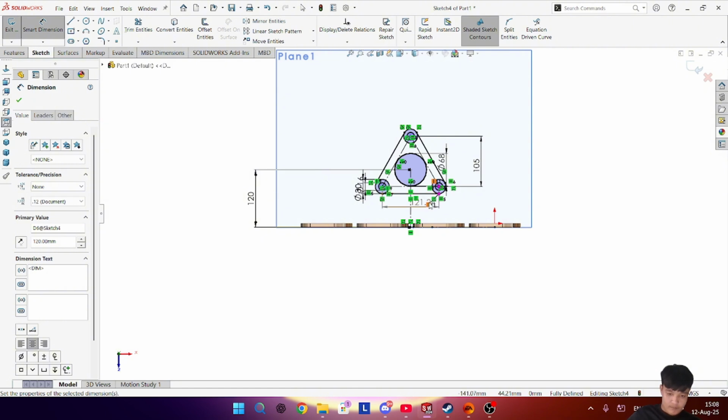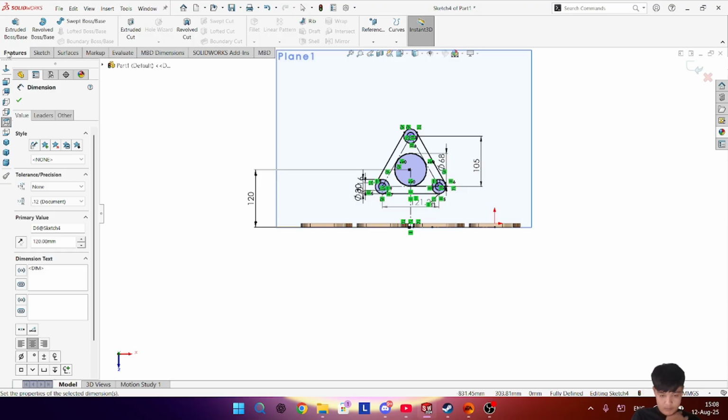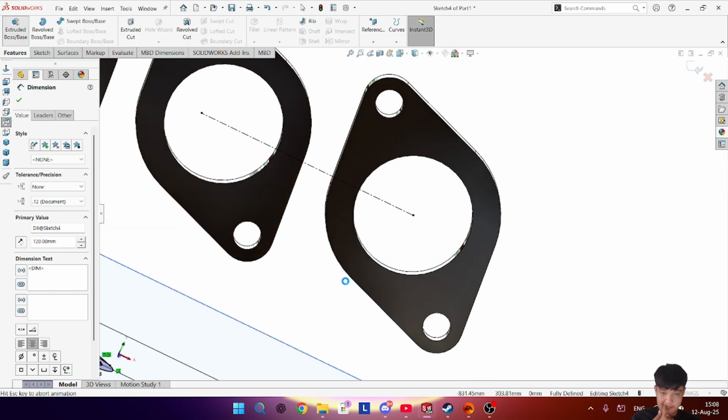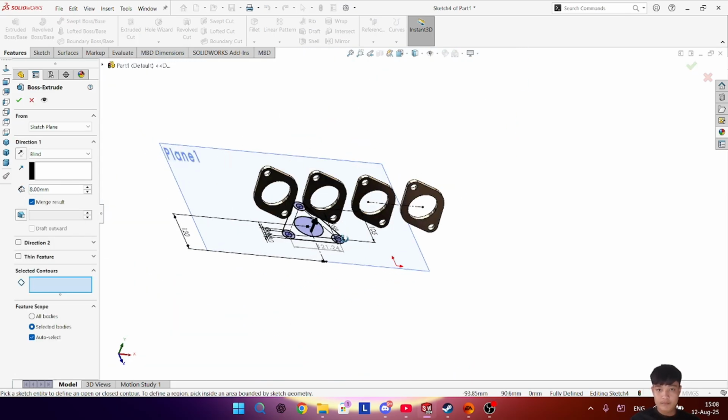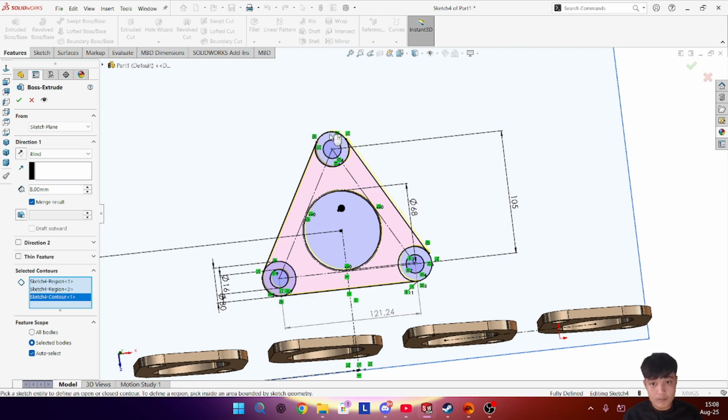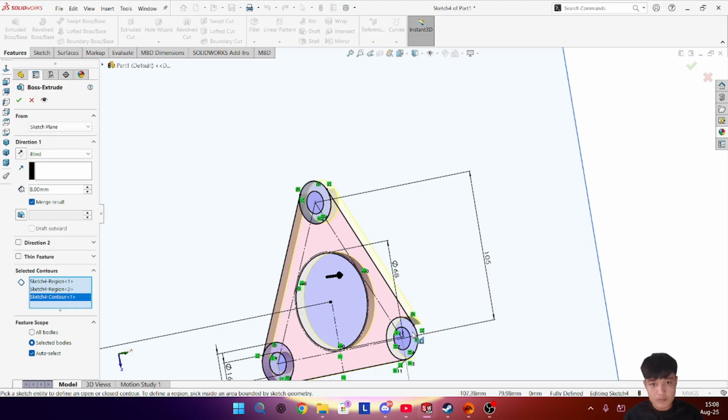Now let's extrude. Select extrude. Select this one, this circles. Inside one, uncheck. Oh, too many regions selected. Select one by one. This one, this one. Here also select inside one. Leave this central holes and make distance 8 millimeter for small result.